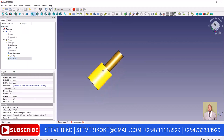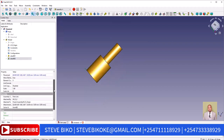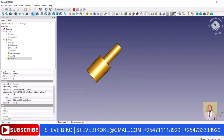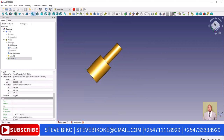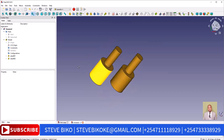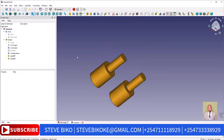Now we have 2 axles conjoined. We are going to separate them. So we move one of them. So I select number 2, go to assembly, then attachment, then position. Then I'll move them along the x-axis. So let's say 15. There. Now we have 2 axles.